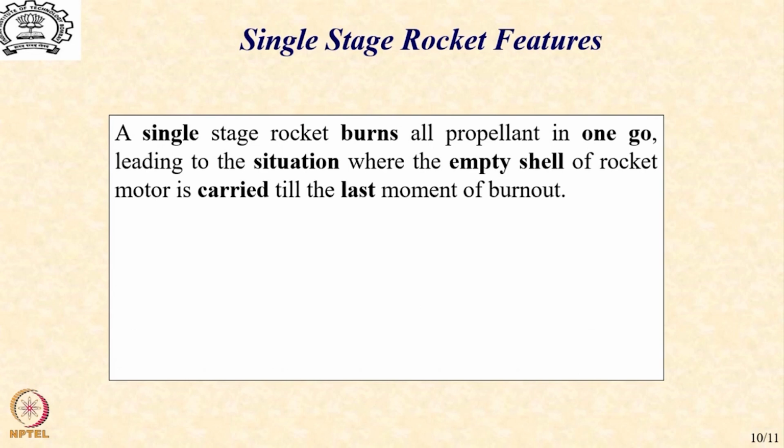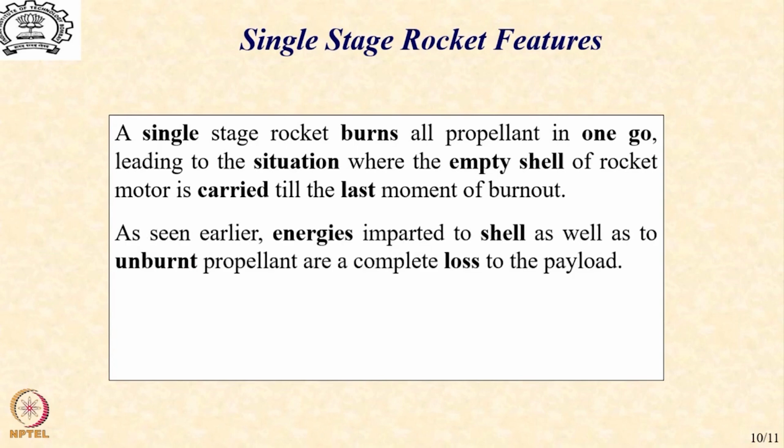But there are certain issues that we now need to look at in this particular mode of operation. The fact that a single stage rocket is going to burn all propellant in one go, the empty shell which you started off with right from the beginning continues with you right till the end, and that mass you are accelerating and imparting the same kinetic energy which is not going to be of any use to you, because your actual spacecraft or payload is going to be a very small fraction of this, which obviously means that this particular mode of operation is highly inefficient from energy point of view. So obviously your losses are going to be significantly high.